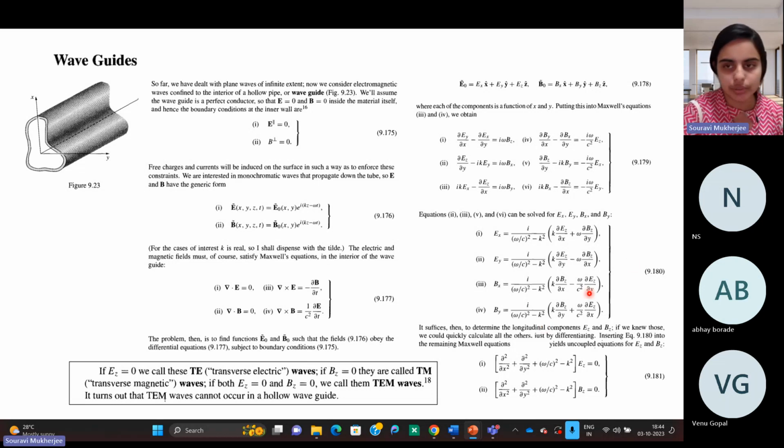This is directly from the expression, you can get it, right? Ez = 0, Bz = 0. So what happens to Ex? Zero. Again Ez, Bz zero. So if you look at it, all these components are zero, right? You can also look at it from here. If your Bz and Ez are zero, then basically there are no waves. You can also get it from these relations, but practically what we found is that there are no TEM waves in a hollow waveguide, right?